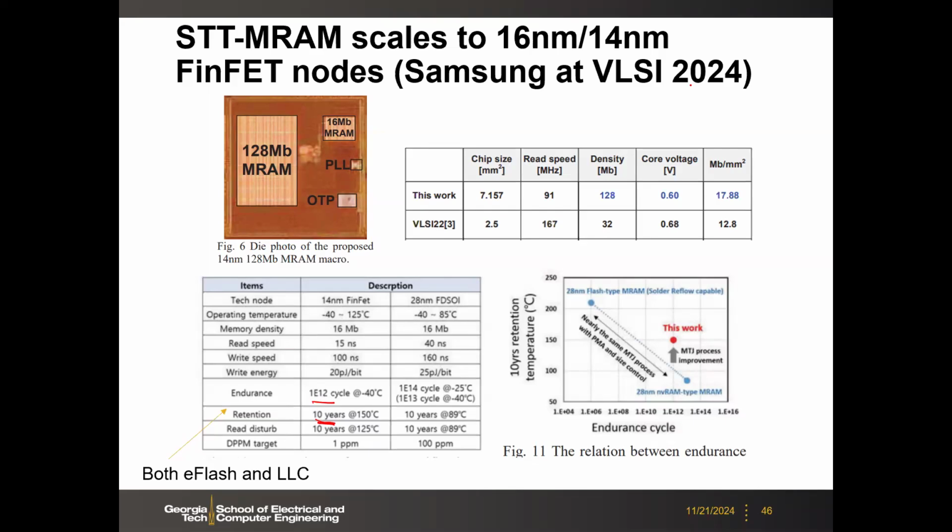Yeah, if I look at this year's IEDM agenda, because I was in the TPC and reviewed all the papers, I remember there was one paper from Samsung that scaled the STT-MRAM to a 10 nanometer or 8 nanometer node. That is the latest progress. It's not published yet, since IEDM is 2 or 3 weeks from now, but I reviewed that paper because I'm a TPC member. The latest progress is that this technology could scale to potentially 7 nanometer. Actually, that is on the roadmap for Samsung and TSMC.